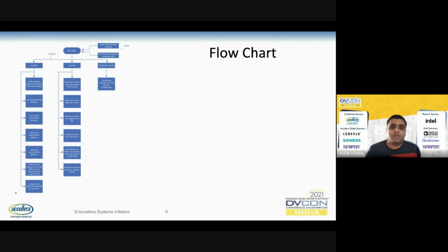For clock fan outs, we are checking various conditions under functional mode and different modes using clock assertion related properties. To validate the clock frequency across the various frequency plans like min, max, intermediate, or boot frequency, we have frequency checkers which we bind on all the clock fan outs. Under the functional coverage collateral, we are generating cover groups, cover points, and cross coverage for PLL configurations, clock dividers, and resets.